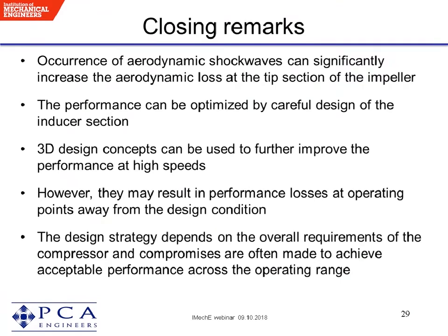The 3D design concepts can also be used to further improve the performance at high speeds. However, they may result in performance losses at operating points away from the design condition, so attention has to be paid to that. The design strategy depends on the overall requirements of the compressor, and compromises are often made to achieve acceptable performance across the operating range.